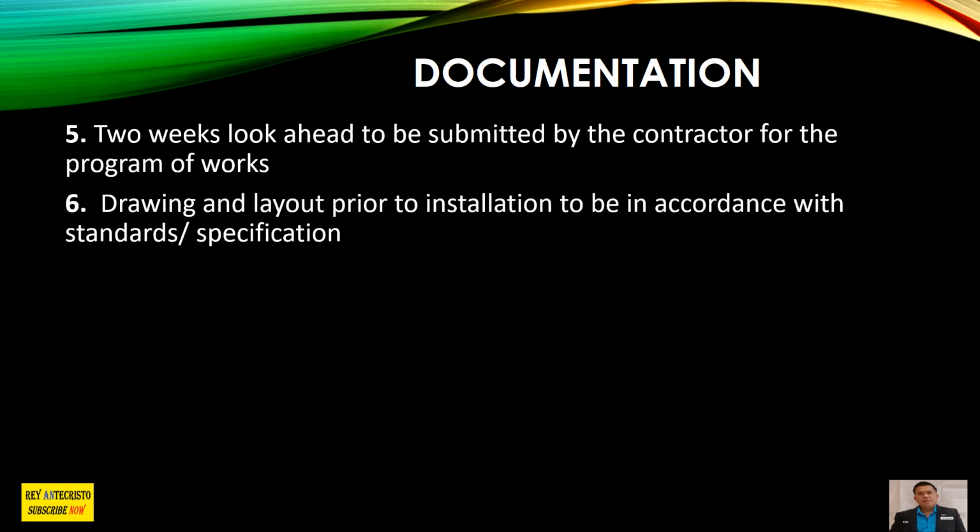Okay, and number 6, drawing and layout prior to installation to be in accordance with standard and specification. Whether you work in different countries, this is always a requirement. As per, we have a FEED drawing, front end engineering design, and also we have a detailed design. So that is coming from there. Prior to installation, all of that is approved by the client, the owner. All these drawings must be approved, and then submitted to the contractor.